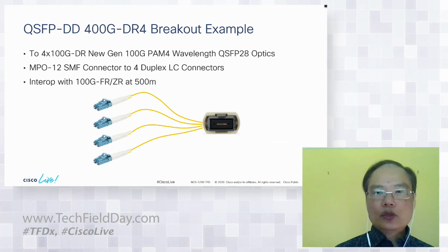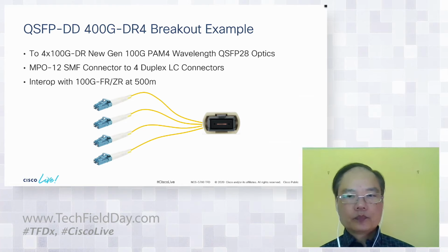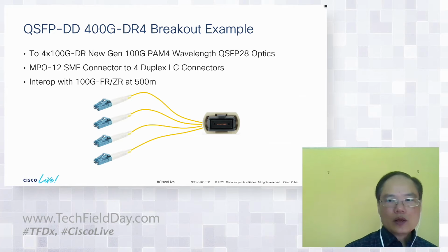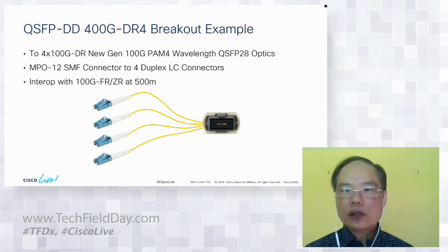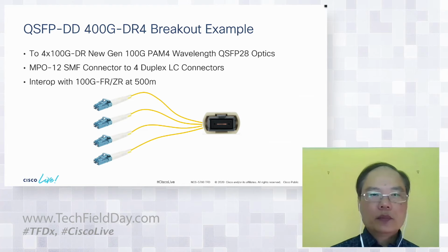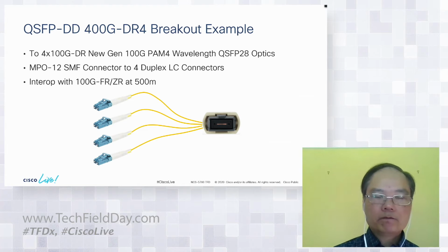And it connects to 4 duplex LC connectors on the other end. It will also interoperate with 100 gig FR or 100 gig LR, but limited to 500 meters.